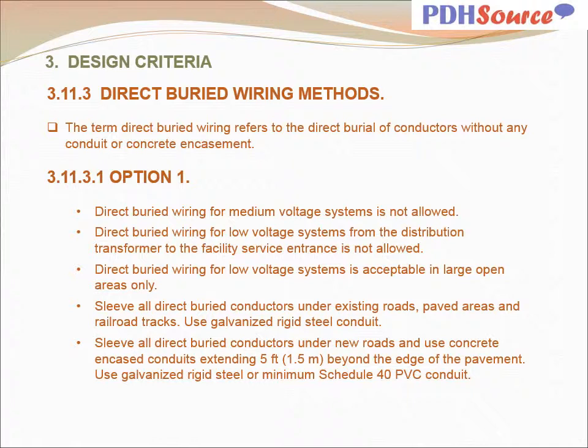Use galvanized rigid steel conduit. Sleeve all direct buried conductors under new roads and use concrete encased conduits extending 5 feet beyond the edge of the pavement. Use galvanized rigid steel or minimum Schedule 40 PVC conduit.